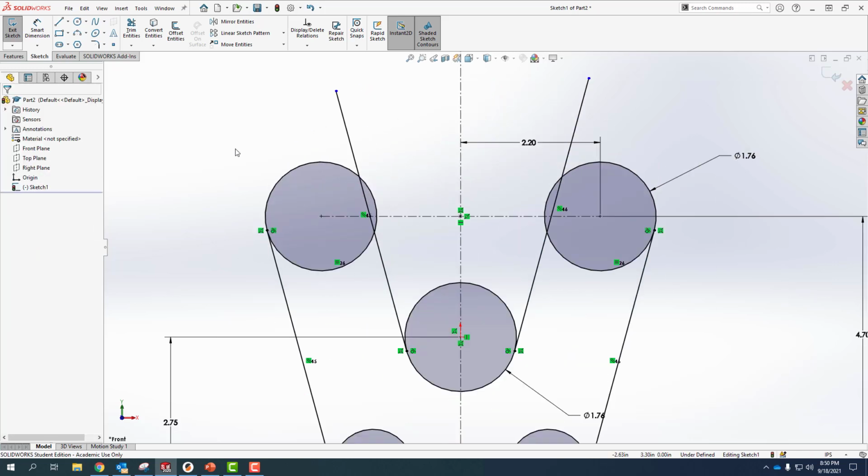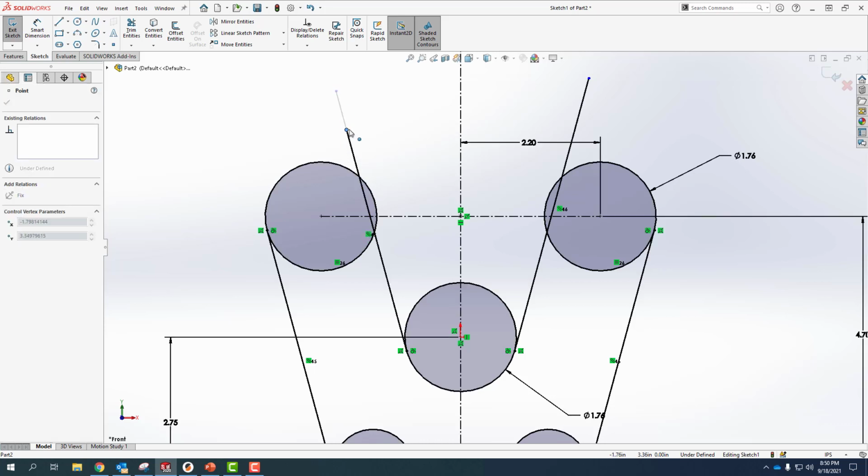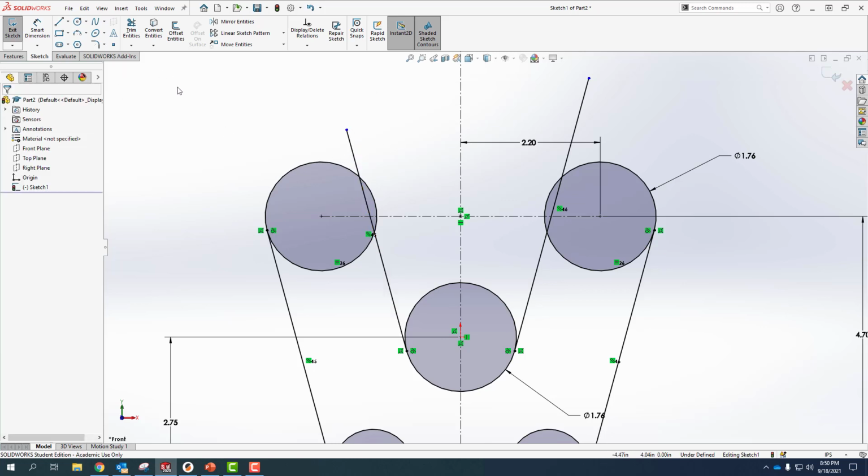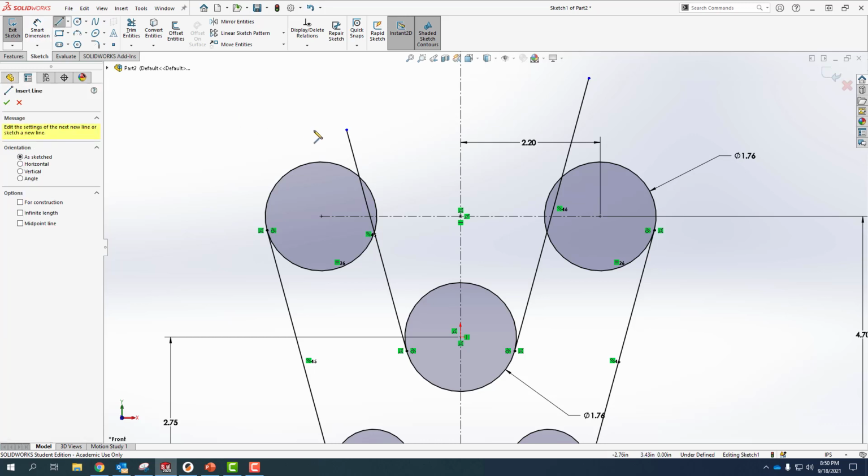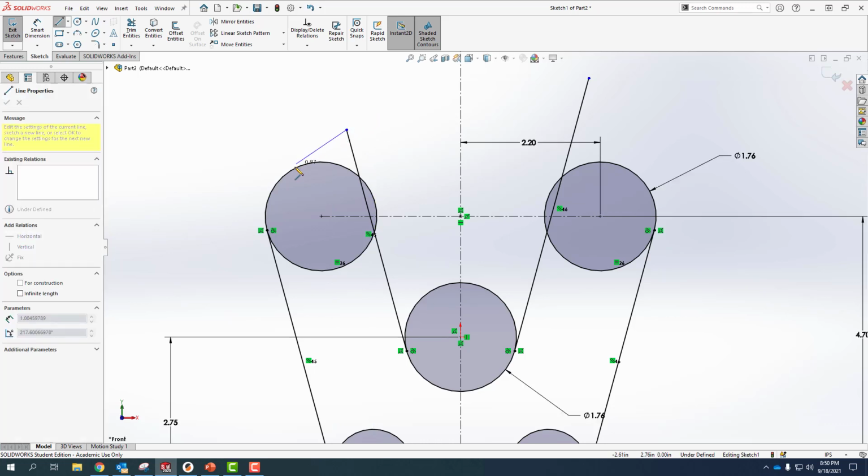And now if you look on the drawing, there's a 90-degree line that's coming out here. So basically it means that there's a line that's going to go from this point to the circle, and then there's going to be a perpendicular constraint. So let me show you how to do that. Again, the trick here is to not worry about where you're putting it when you drop it. Then you will put on the sketch relations. So I'll select here and just select the circle.